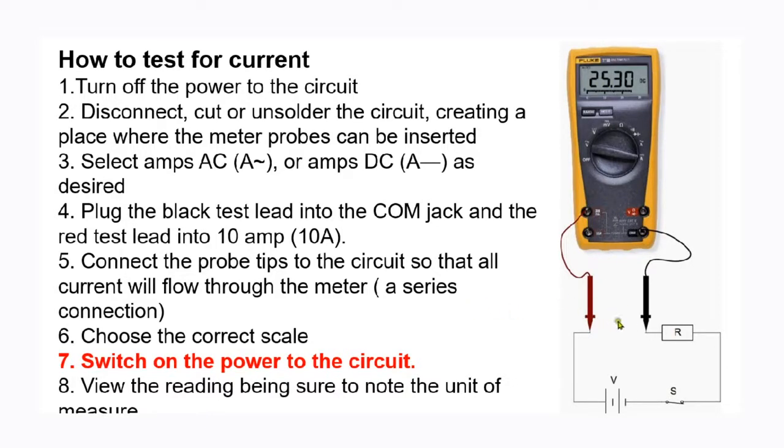Right? Students, please take note as well. Whenever we test for current in industry, we do not use this method. We do not test for current like this, where we go and break the circuit. This method is only used in laboratories or when we are testing currents of very small values. Right? Don't go and use this method in industry.